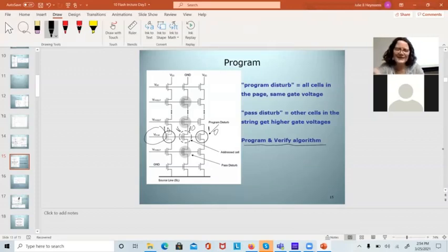They're all like that. Okay, so basically this program disturb is going to give me errors in my readout. So I need to store data in extra bits and something like Hamming codes to actually be able to verify I got the right data. And so if say the verify algorithm doesn't work, like this is just a circuit. Right. Like if the verify algorithm doesn't work and a program disturb occurs and it writes everything to zeros, does that basically mean it doesn't write correctly?